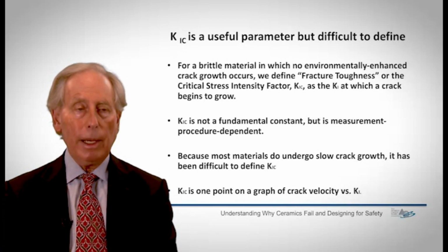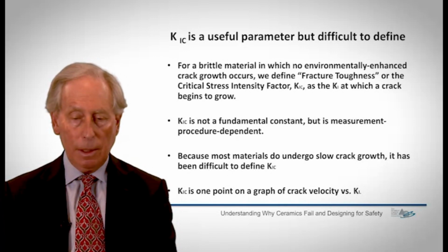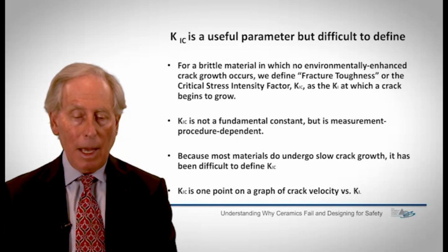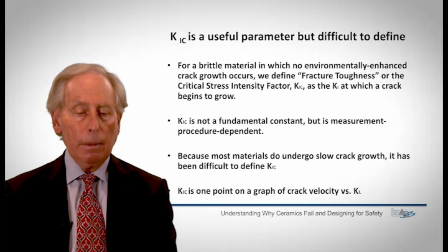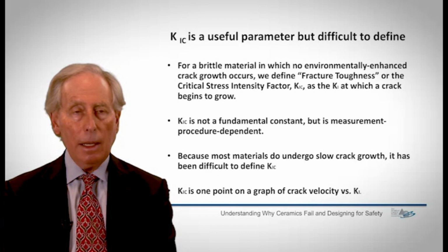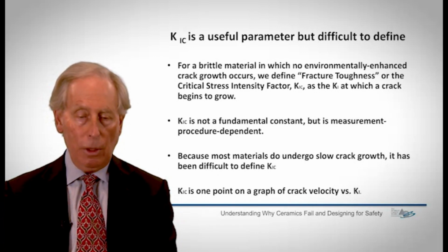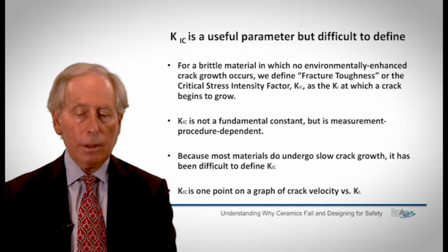It enables us to pick out exactly how we want to measure things. And I make the point here that critical stress intensity factor for any given material is not a fundamental constant, but is measurement dependent. And I'll show you lots of measurements in the next few slides.